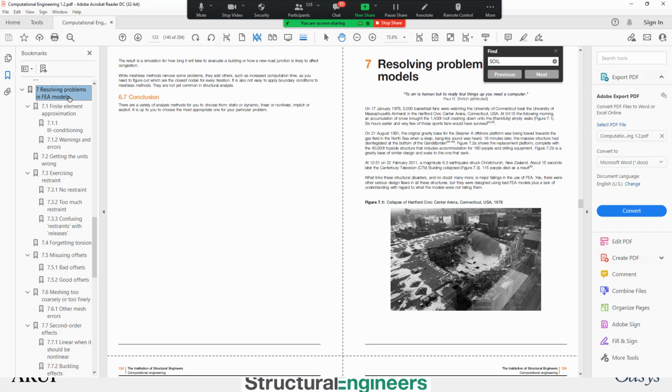Great. Back to the mesh sizing. Are there any consequences of using too small a mesh size, if any? Yeah, the consequences of too small a mesh size: there are the unrealistic moments at supports. There is the running time. If you halve the size of the mesh, you've got 4 times as many elements and more runtime. There's also a point where the accuracy goes away. Yeah, those are the main things.